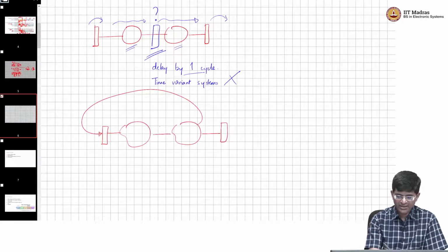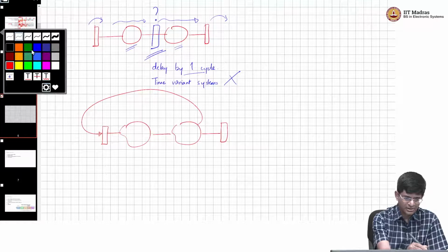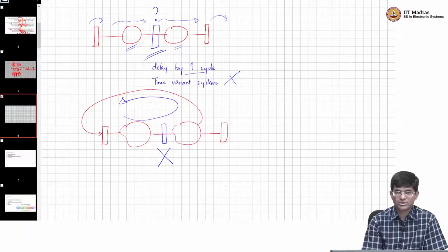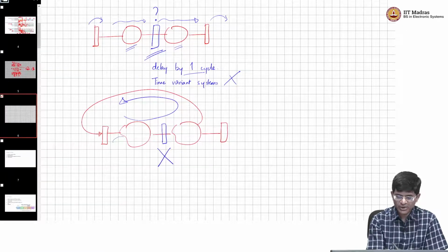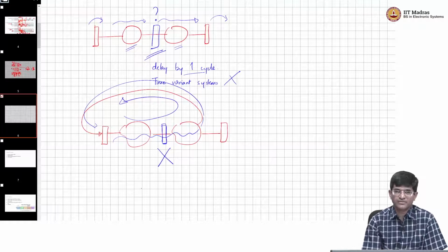Now, if I say I am going to try and insert a register out here, this has actually changed the functionality completely. This is wrong, I cannot do this, right, because what has happened is there was some computation that was going through and was expected to come back at this point. By adding a register out here, I am actually changing the functionality in a very non-trivial way, right.